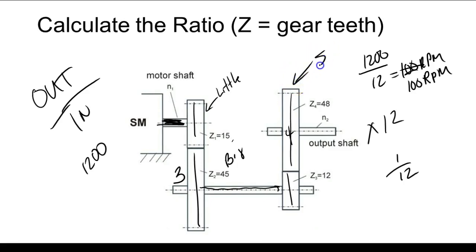It allows us to stop this and not stop this. That's what a clutch does. And also we can use it to vary the torque. So a clutch basically slips. It allows slip to occur in the system. So it allows the output to stop completely and then your prime mover does not stop.